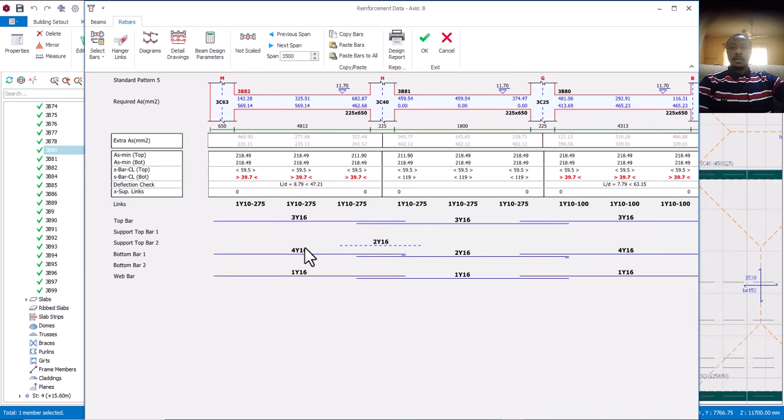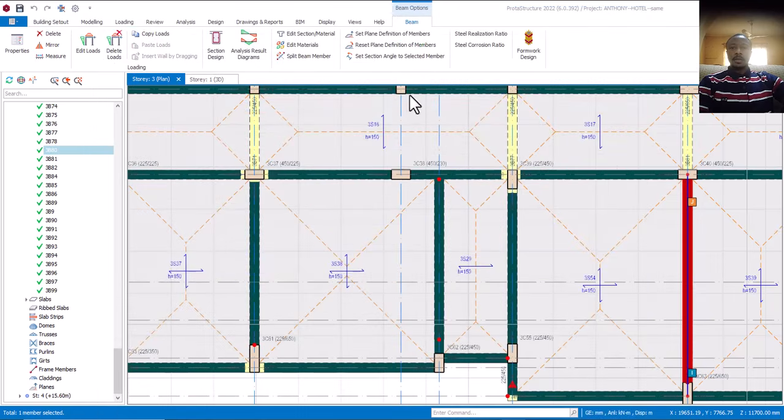When you are having too much number of reinforcement and your width is small, it will not be able to accommodate it. Or your depth is small, or it's deflecting. Those are the reasons why you cannot ignore it. But after you click on OK and you check all of these things, if they are intact, you can let go of that and move on. Is that okay? All right, that is fine.